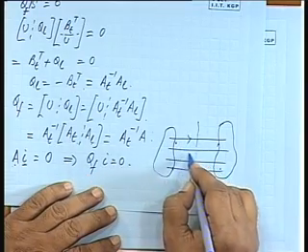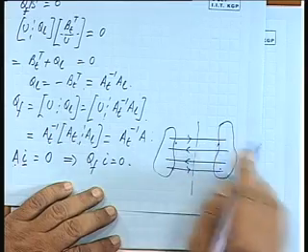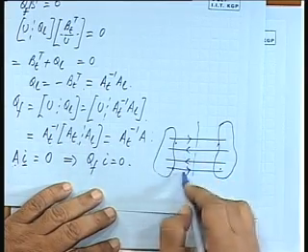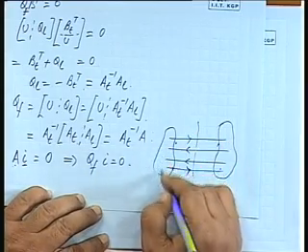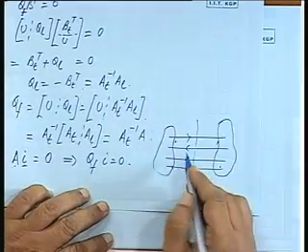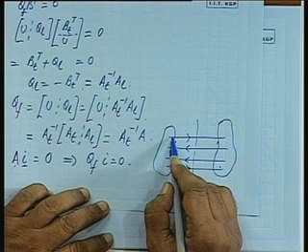So currents going here, here, here, like this. Say there are many currents flowing through this. So currents flowing through only these elements will be non-zero. Other elements, there can be other elements here, but they don't come into picture. So far as this cut set is concerned, the algebraic sum of these currents will be 0.